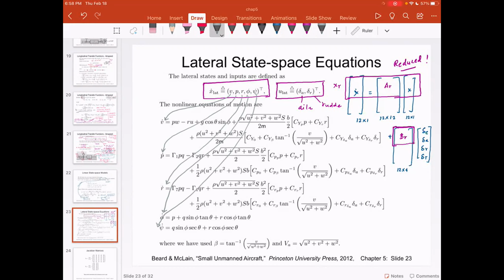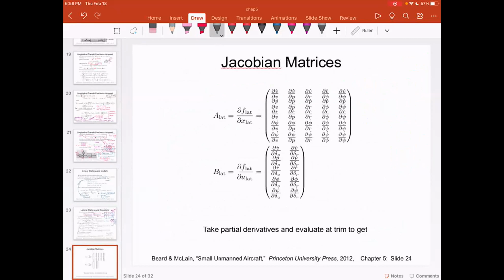A very simple approximation is, for example, if I have sine theta, I will approximate it to theta. If I have cosine theta and my theta values are small, I would approximate that to 1. So basically I would use a Taylor series expansion to come up with a simplified expression of this nonlinear set of equations. And believe it or not, this is nothing but the Jacobian that we talked about. And this is what we studied in Robotics 1.